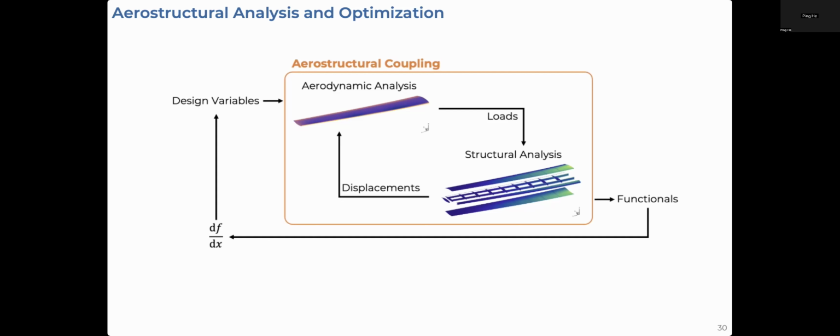We'll apply this methodology to the NASA Tiltwing concept vehicle to design and optimize this vehicle configuration using DAFoam. This vehicle is an 8-propeller vehicle with propulsors distributed along the wing and horizontal tail. In hover, the wing and the tail propellers are oriented vertically so that it can take off vertically and land vertically, and in cruise, everything is oriented forward like a conventional aircraft, so it can fly like a normal aircraft.